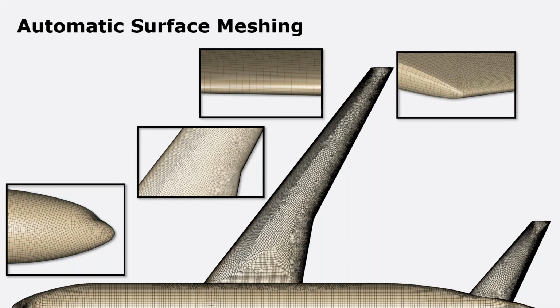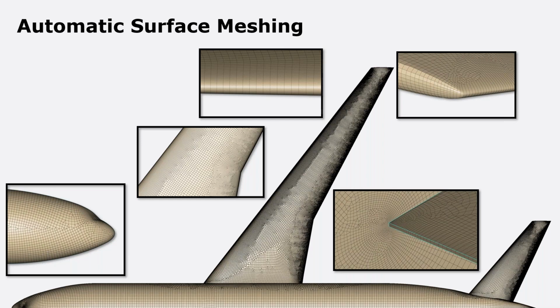You can see we can wrap really smoothly around features like the wing tip, and then that blunt trailing edge is a long, slender surface. We can automatically apply our structured meshing best practices there to capture that blunt edge and then pack points into that wing root region. And like I mentioned, this is all out of the box, all handled automatically.